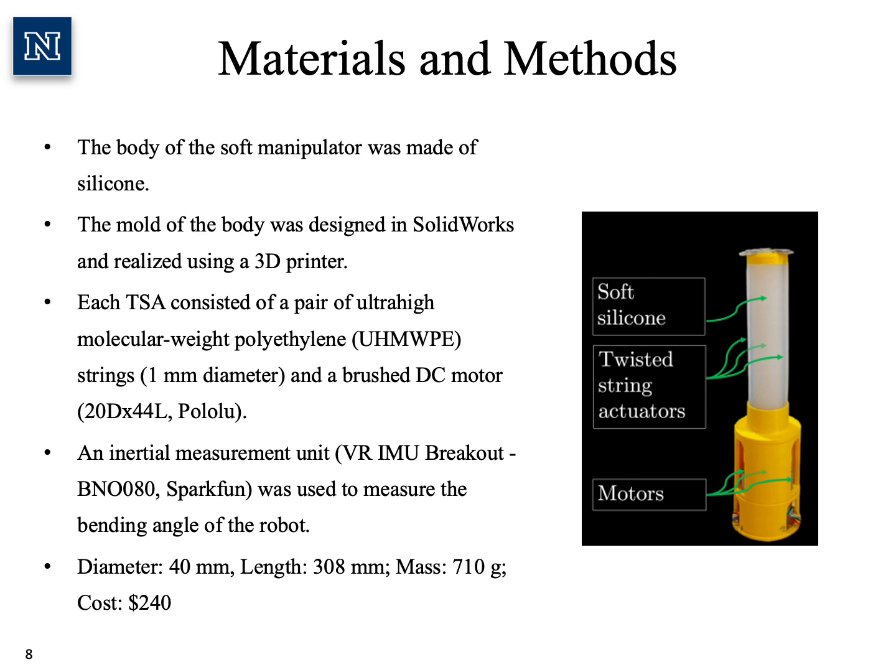The soft body of the robotic manipulator was made with Smooth-On 0050 silicone. This silicone was selected due to its predominant use in related literature and also because it was not toxic and safe to handle. The mold for the soft body was designed such that it was easy to 3D print and was disposable once the body was cast.